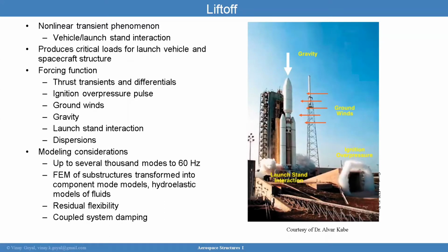The liftoff analysis typically requires a nonlinear simulation to properly define the launch pad launch vehicle interface, and the response of the system can be derived in a nonlinear simulation. It can also look at interface forces from this simulation, which could drive additional analysis. So, because of the need to define launchpad interface forces, the displacements at this interface need to be defined. You have to get that right, and those flexibilities need to be correct. Otherwise, there could be a problem.